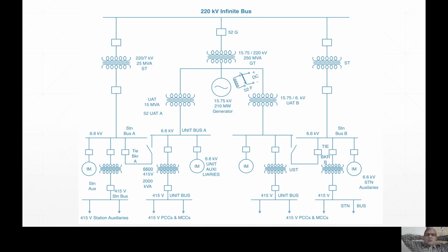You see, you have to use a wagon tippler. The complete wagon is made upside down. So one big 415-volt induction motor is working to topple the wagon tippler. Right. Then that coal that is coming has to be crushed, because that coal you cannot feed to the boiler. So it has to be crushed first by a crusher. In the primary crusher it is crushed to a certain extent. In the secondary crusher it is crushed further. And then in the coal mill it is powdered.